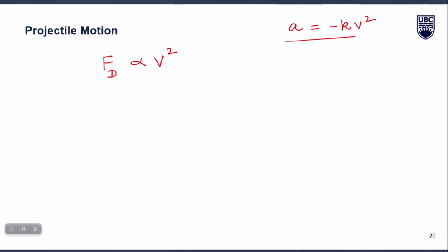They have a property called viscosity, and the property viscosity is responsible for applying a resisting force whenever a solid object is trying to move through them, right? So in that case, the ship was experiencing a resisting force, and resultingly a resisting acceleration or retardation, which was proportional to v square, right? And now I am also telling you that when something is moving in air and you want to introduce the drag into the equations of motion, that drag force is generally proportional to the square of velocity.